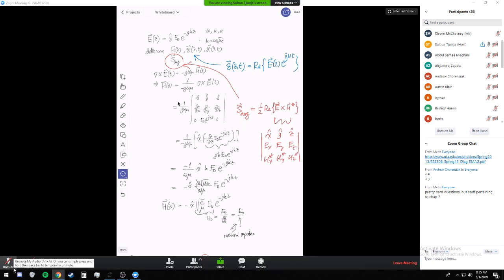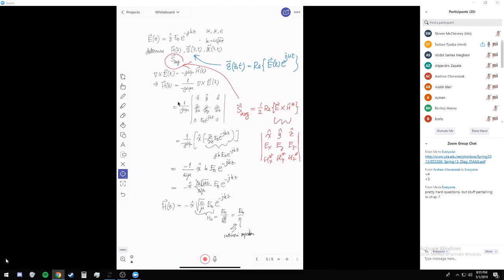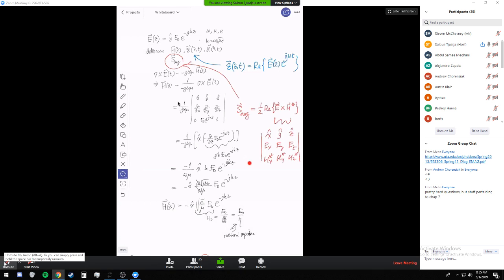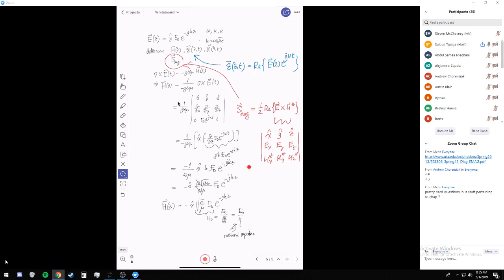So that's a typical question for chapter 7. In other words, do you understand what we mean by plane wave, and the properties of a plane wave? The properties include what the frequency of the plane wave is, what the wavelength is, what the phase velocity is, right? And if I give you the electric field, can you solve for the magnetic field and vice versa? And can you tell me where the power flows? That's about it. So a key thing is understanding the properties of a plane wave and how the different components link.